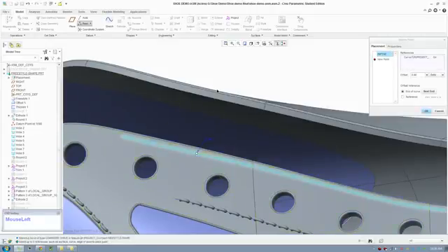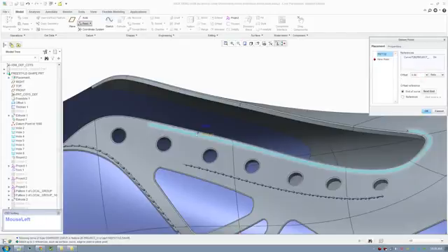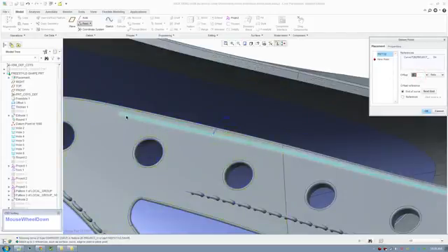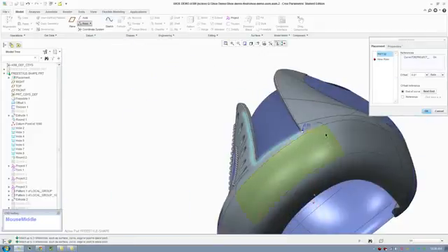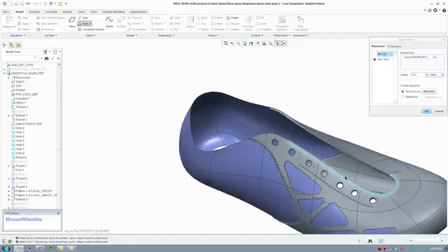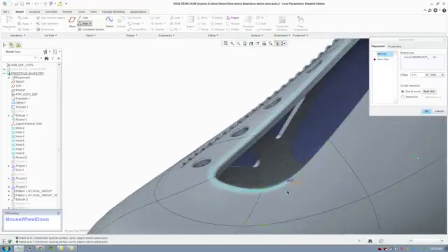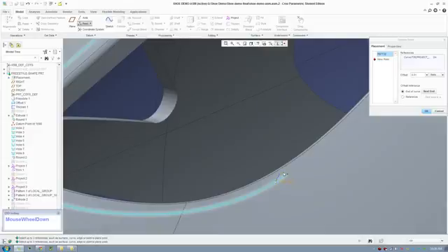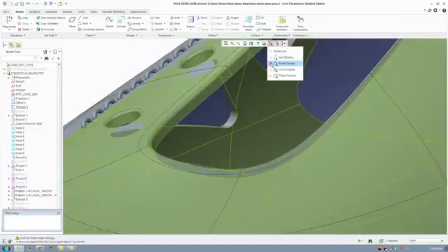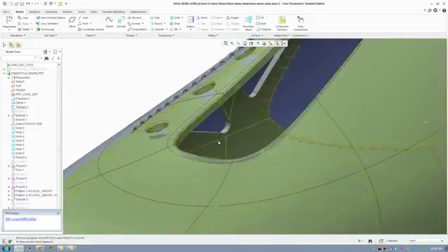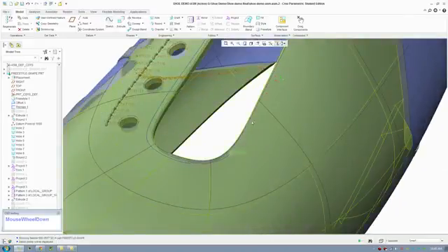Now this point is going to travel along the whole curve, and if you put the point not on the end but just off the end, you put in an offset value. So that's a dimension, and that's really important for us to be able to pattern along that dimension, and it's going to follow along the curve because the point is always on the curve. So just create the first point there, and we can show the points by turning the points on here. Alright, next, I'll just pattern that so you can see that now.